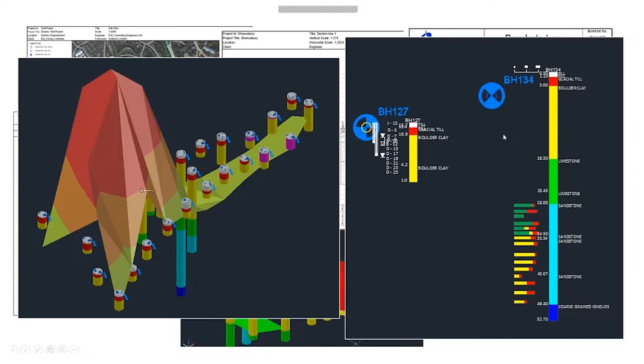On the right-hand side, we have some of the more sophisticated log strips that HoleBase SI and the Civil extension give you. So you can't do this with the Geotechnical Module, but here, when we were talking about hole types, this one here is a rotary coring hole. So this is my coring recovery ratios. In fact, this wasn't a particularly great hole by the looks of it, looking at the ratios coming out at the bottom down here. But how this data looks and what you retrieve back can all be designed inside HoleBase and added into Civil, and then every time you use it, it pops up this information. So there we've got the recovery data.